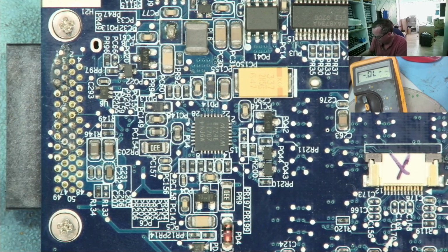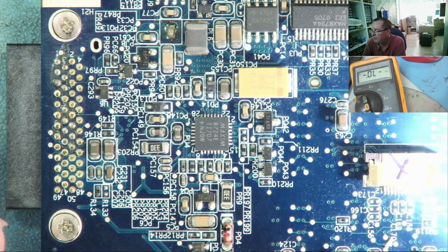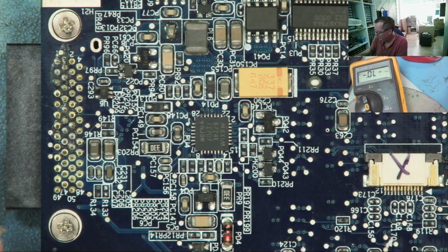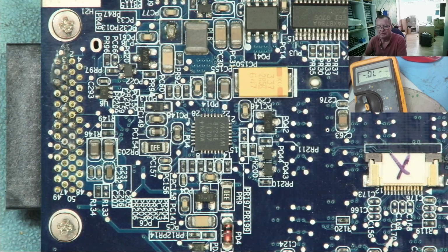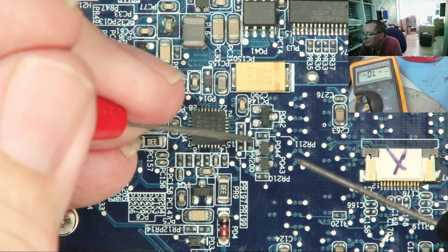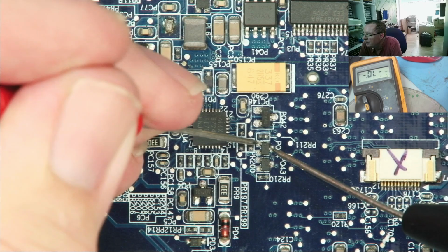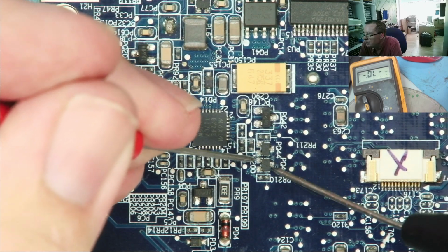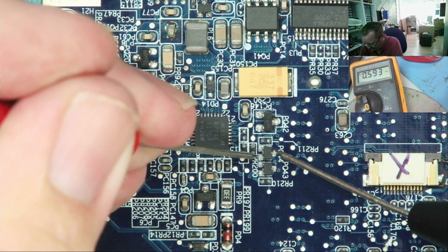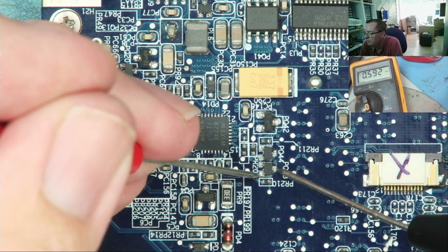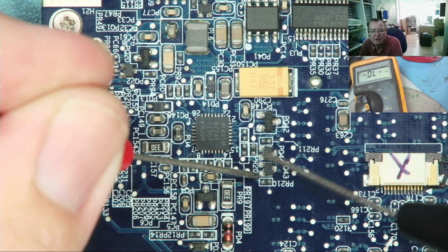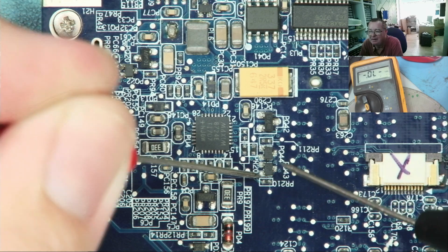These two devices are both the same. KP. KP. Without looking up the data sheet, we can compare the two. Now, I'll put the red lead on here. Nothing. Same with this one. Nothing. Red lead on here, 0.593. This one, 0.591. Almost the same. This is almost certainly a parasitic diode, okay?